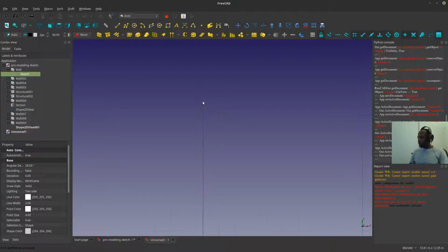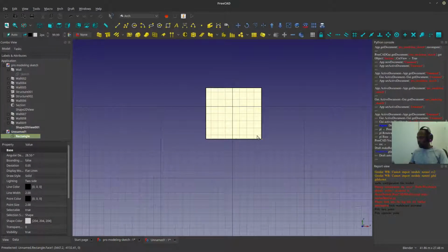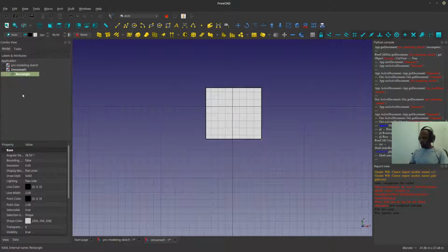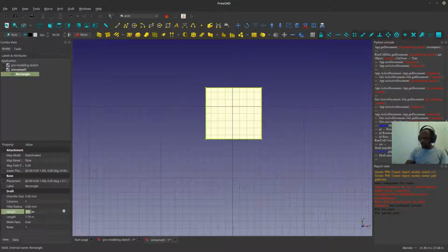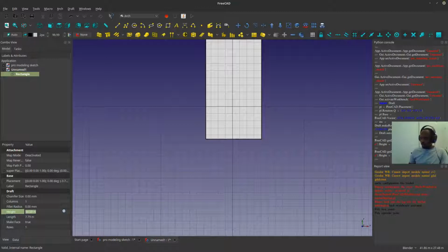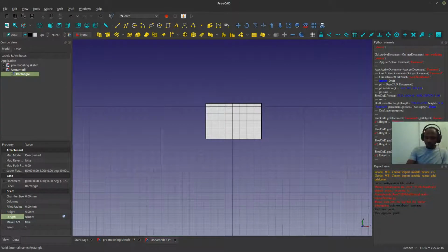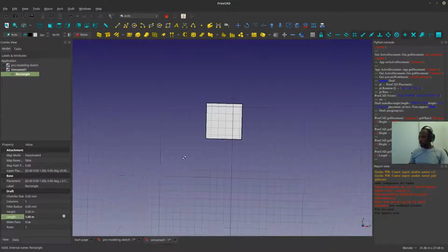In this example, I'm going to go directly to the sketcher. Actually, I want to cheat my way and start from the Draft workbench. I want to draw whatever shape I want; that's going to be the shape that guides me. I might want to give it some specific dimension, just to be precise. So maybe 5, no, that's too much. 5 meters by 5 meters, like this. Okay, so now I have that.